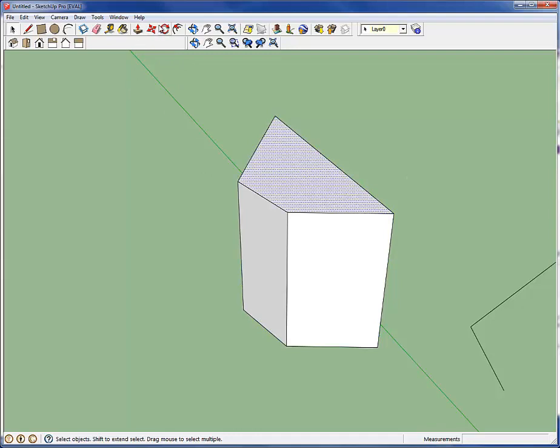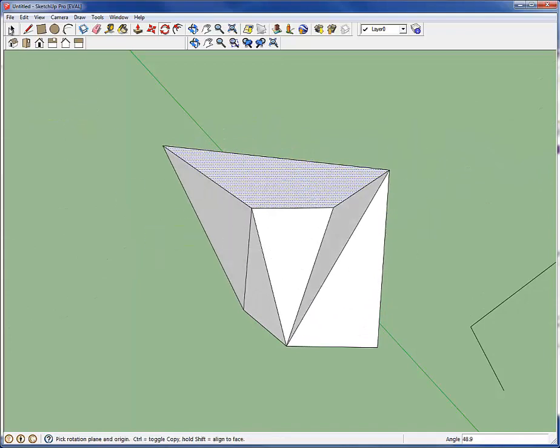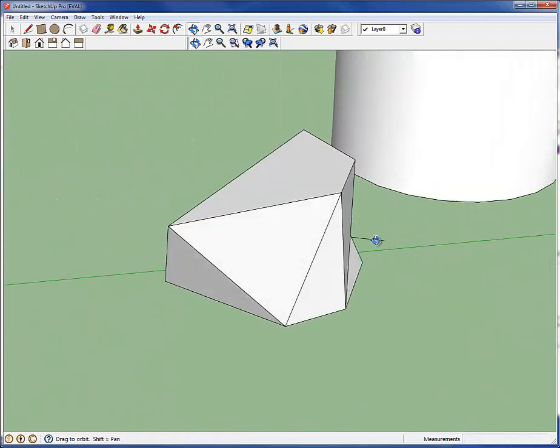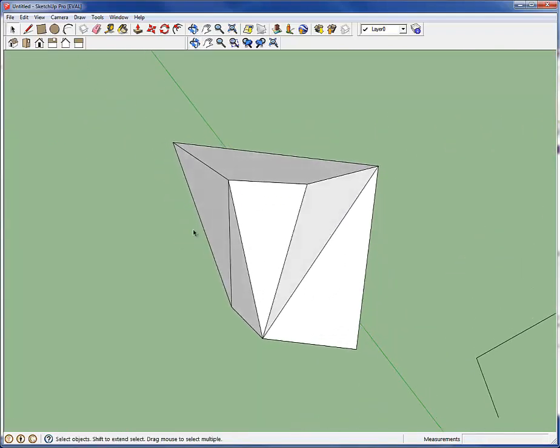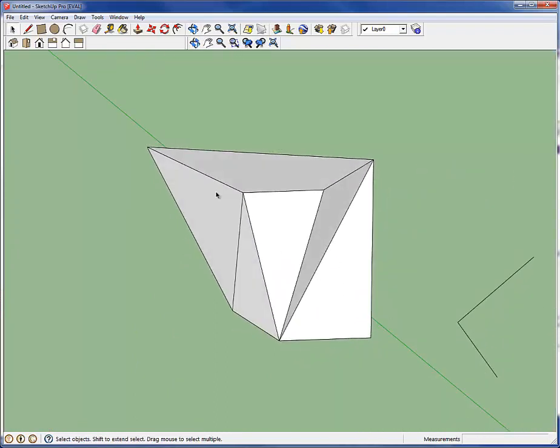If we come in here, we can rotate, we can pick this up and grab it. You can see the Inference Engine is going to automatically create all these nice folds. As long as we're paying attention and we know how it's going to act, that's great. If you don't know how it's going to act, that's something you want to pay attention to as well. And there's no way to turn off the Inference Engine, so it's absolutely there to stay. So despite all that, you've got to be really clever about how you end up using it.